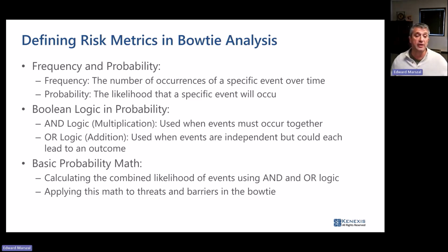Now, if you want to go into more detail on probability addition, especially when related to failures, I will point you to the Connexus SIL verification training class that goes into all of the nuances of probability addition, because when all you do is add the probability numbers together, you are overestimating the actual probability because you're ignoring the probability that two events will happen simultaneously.